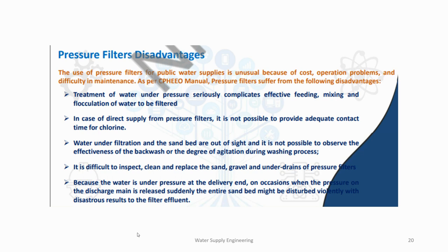Because chlorine, once it is added, won't be effective in a fraction of a second. So even we have some guidelines that there should be some amount of chlorine that is left behind after the entire treatment, till it reaches the consumer end. So when we are doing filtration through pressure filters, it is difficult to maintain this contact time.